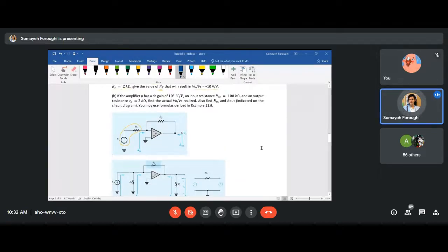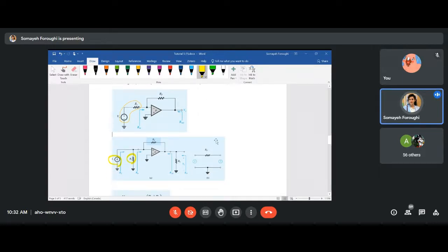So what I did here, I replaced that Vs and Rs with Is and Rs, right? And so everything else stays the same. So what is Is here? Is will become Vs over Rs. And listen, guys, in this example, we do not have that RL, so I'm gonna clean it.